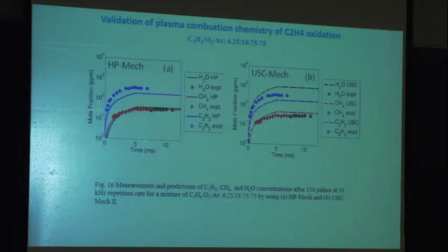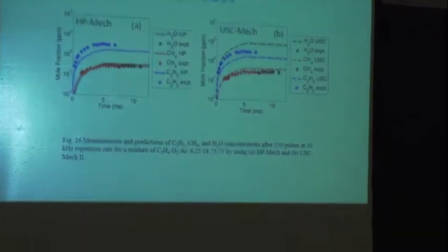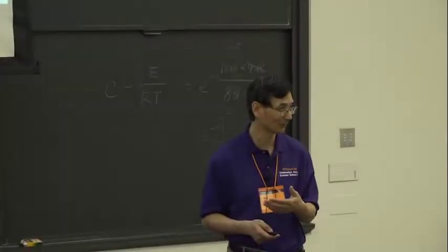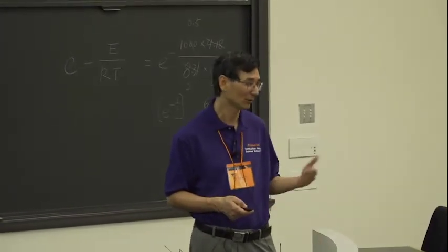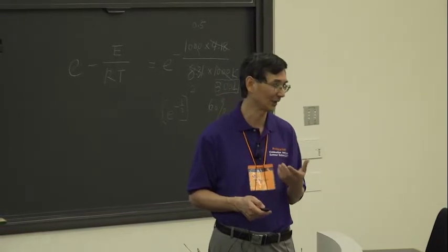So for plasma mechanisms, it's better to use an elementary rate-based kinetic model, so that you know what is going on. Do not use an optimized kinetic model to try to explain the phenomena, because it's beyond the temperature range in which most combustion models are validated and developed.